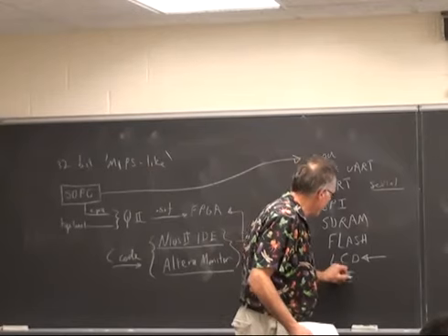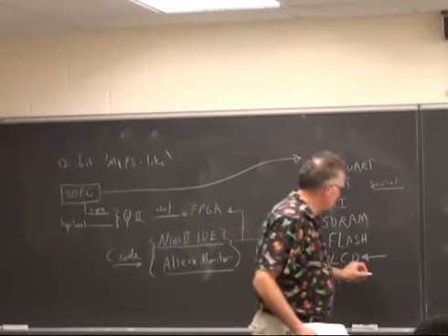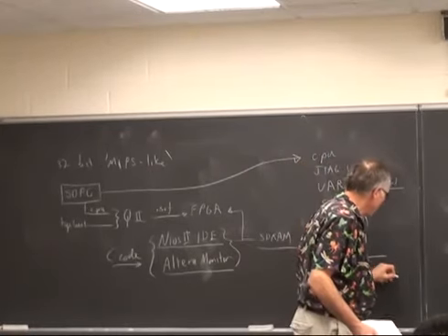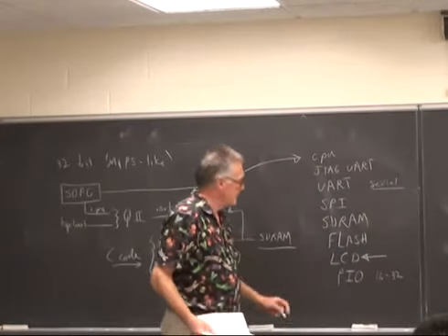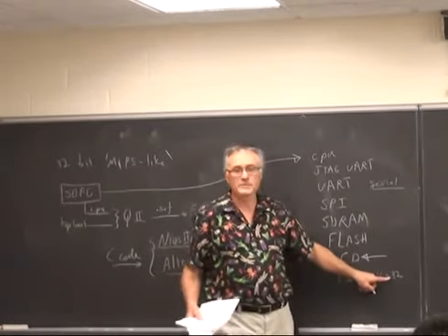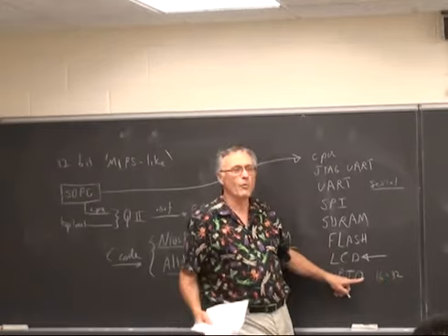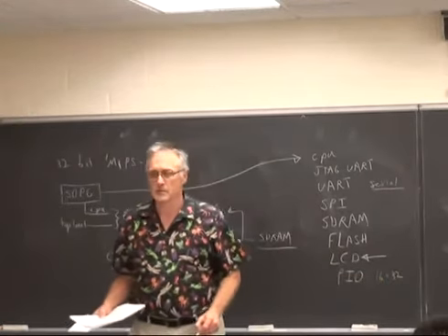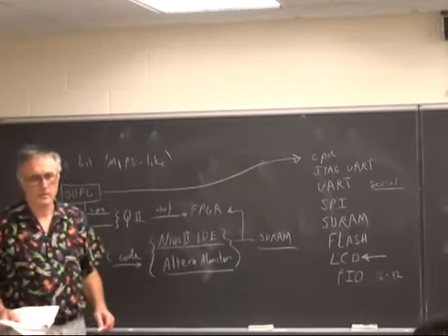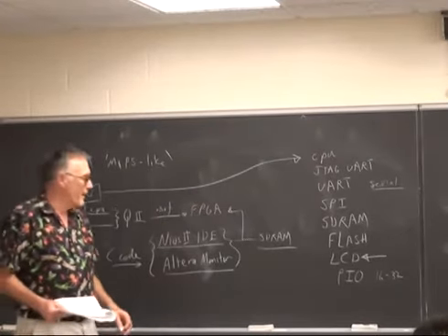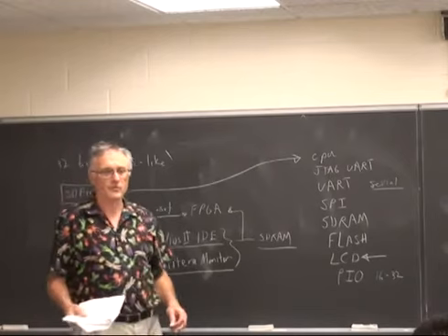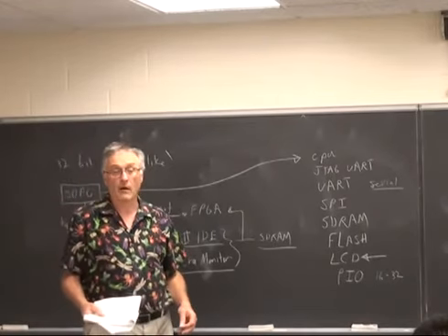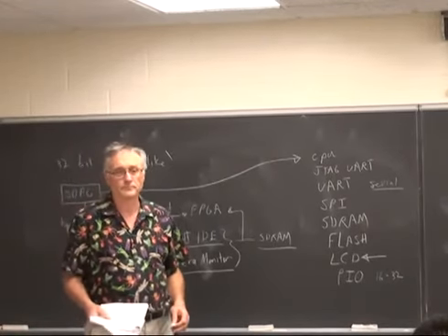There are parallel I/O channels. These can be 16 or 32-bit. I think they can even be 8-bit. So you can build as many of these as you want. You can have as many I/O channels as you want off of this chip. Unlike commodity microcontrollers that limit you to 2 or 4 or 8 channels, you can have 100 I/O channels if you want.